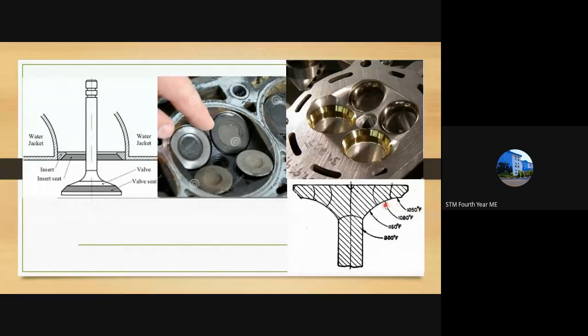Then on going downwards, 1080 Fahrenheit, 1150 Fahrenheit, but on the stem it will be cooler, that is 800 Fahrenheit. So you can see that the brunt of the temperature will be here. From the center, the closest point will have 1050 degrees Fahrenheit, while these points will have 1080 degrees Fahrenheit, then 1150 degrees Fahrenheit. This is a basic temperature distribution. I just want to show how the temperature differs across the valve regions. So the stem will be much cooler.